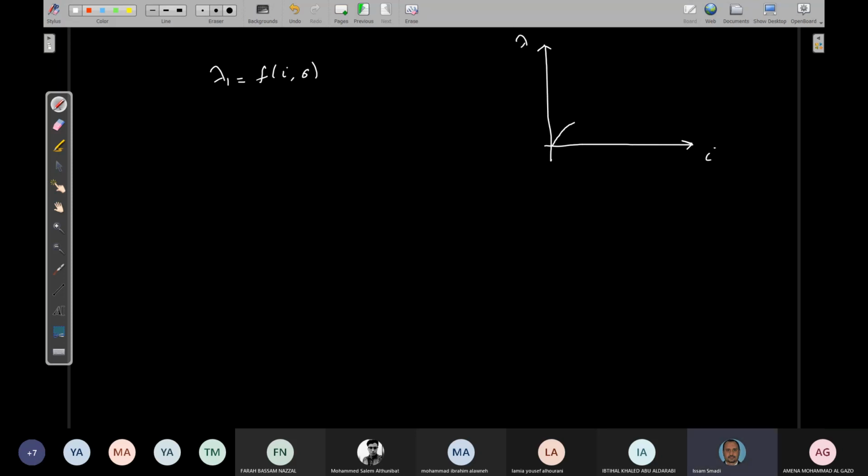And let's assume that this is the magnetizing curve, which is nonlinear. Now, let's assume that this one happens to be this space equal to this space, then omega f will equal omega c. But in general, omega f is not equal to omega c in a nonlinear system, but for a linear system, omega f must equal omega c. Understood?